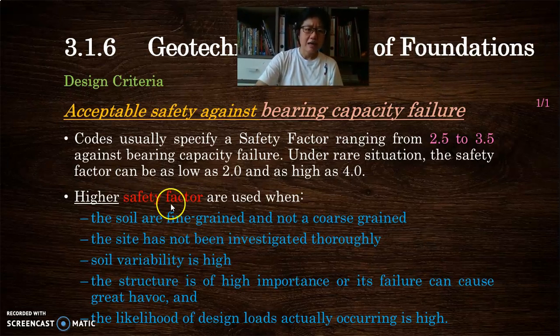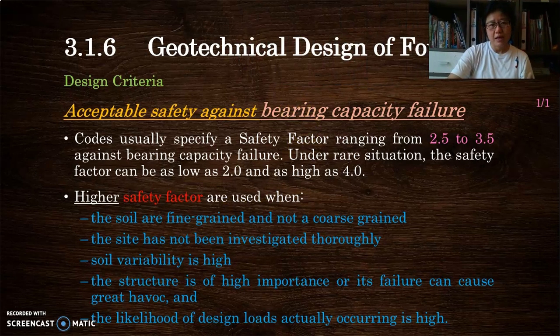Alright, and higher safety factors are usually adopted when your soil is fine grain. Fine grain means clay. Everybody knows that when it's clay that you find on site, you do not quite like it. It can be quite dangerous, soft like plasticine or worse. The site may not have had a very comprehensive investigation done, so the SI is not completed, for whatever reason, you can't get hold of it or things like that. So because you are not sure of the foundation soil, you may want to up the safety factor. The variability of the soil is high. From one part to another, you have all the boreholes in, and you still get all the variation.